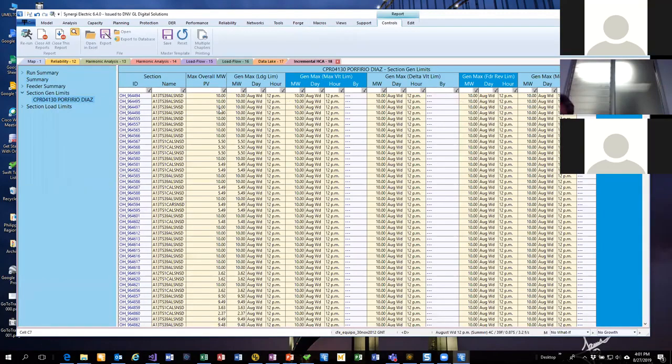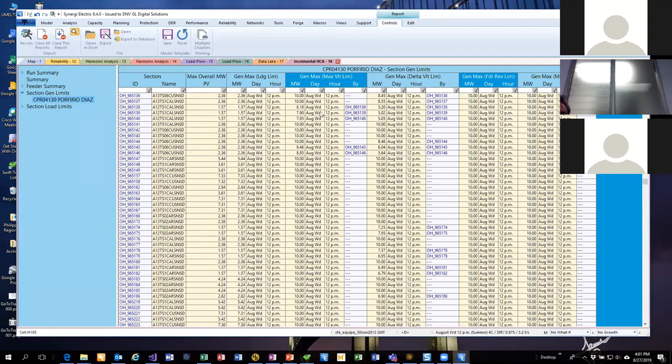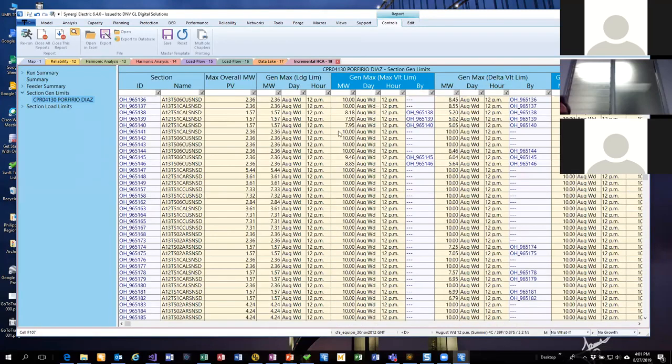we can see, yeah, this is an odd circuit here, but most of these are at my maximum, but here I've got this section here, I'm down at 8 megawatts, and here's the limitation. So I can see I'm hitting a maximum. The 5 categories that I had mentioned here, the overall limit is in this column, and then the loading limit, this is the thermal limit,